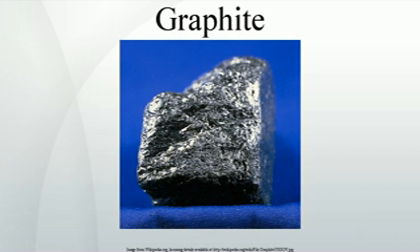When a large number of crystallographic defects bind these planes together, graphite loses its lubrication properties and becomes what is known as pyrolytic graphite. It is also highly anisotropic and diamagnetic, thus it will float in mid-air above a strong magnet. If it is made in a fluidized bed at 1300 °C, then it is isotropic to turbostratic, and is used in blood contacting devices like mechanical heart valves and is called pyrolytic carbon, and is not diamagnetic. Pyrolytic graphite and pyrolytic carbon are often confused but are very different materials.